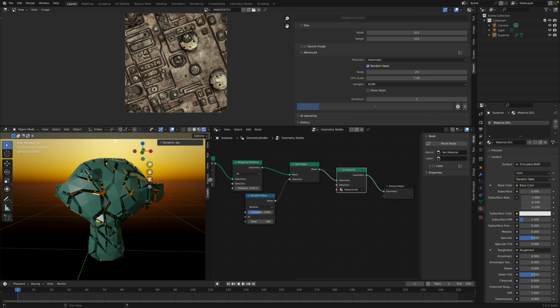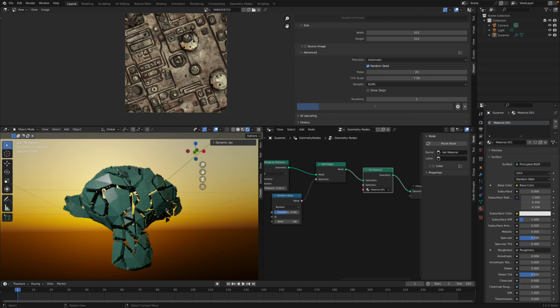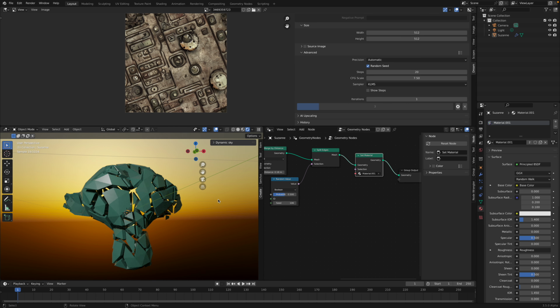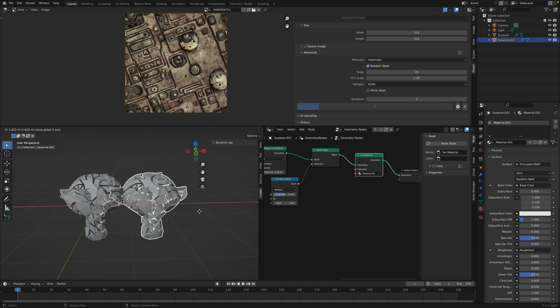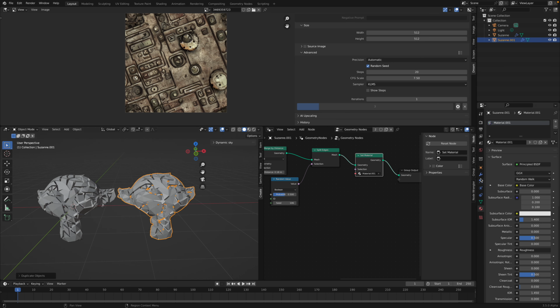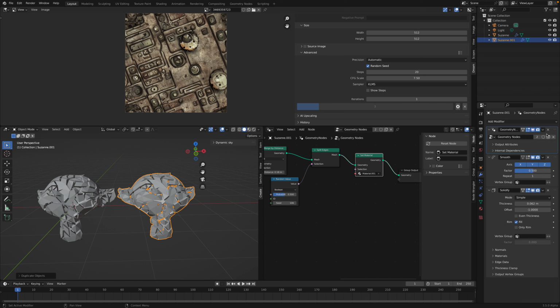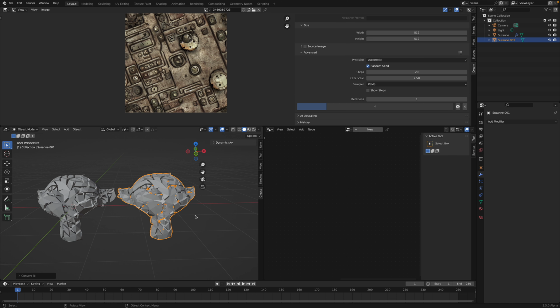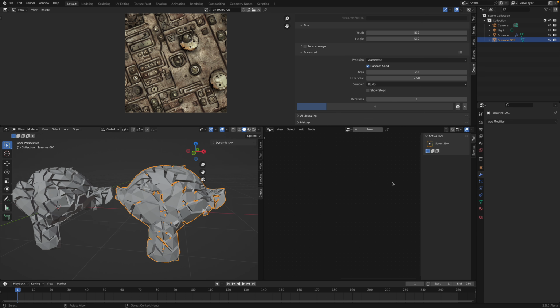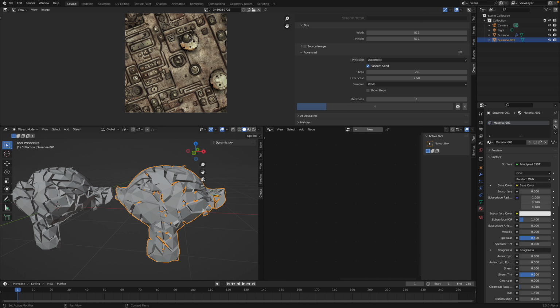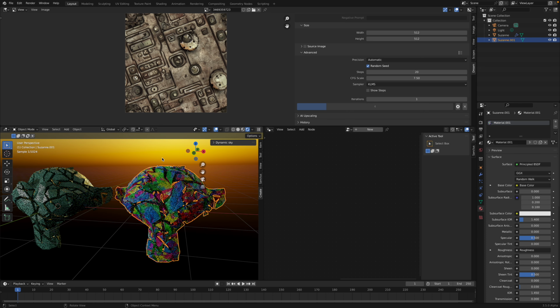Okay, we apparently lost the UV. We need some kind of quick way to do the UV with geometry nodes. In the meantime, I'm just gonna right click, convert this to mesh, and F3 smart UV. Boom. Reassign the material. There we go. That's what I want to show you.